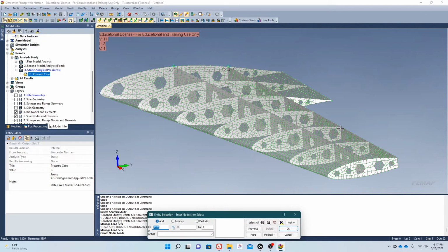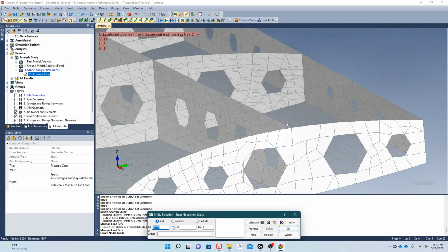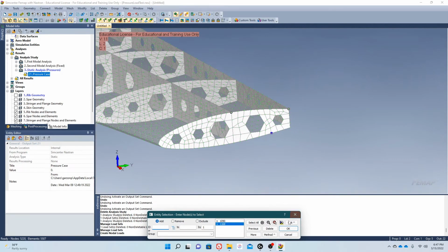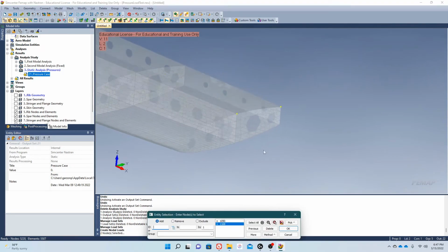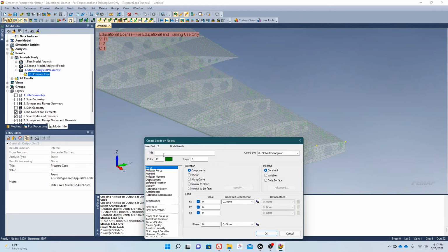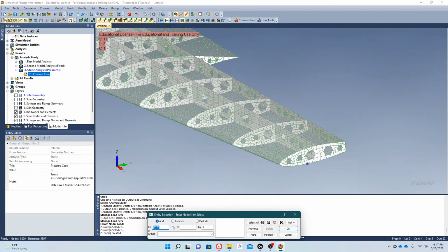So let's specify some loads here at the nodes that intersect the front rear spar and the tip rib. So those nodes right there. You press OK, and let's do this nodal load positive Z global, and let's do 500 pounds each in the Z direction.